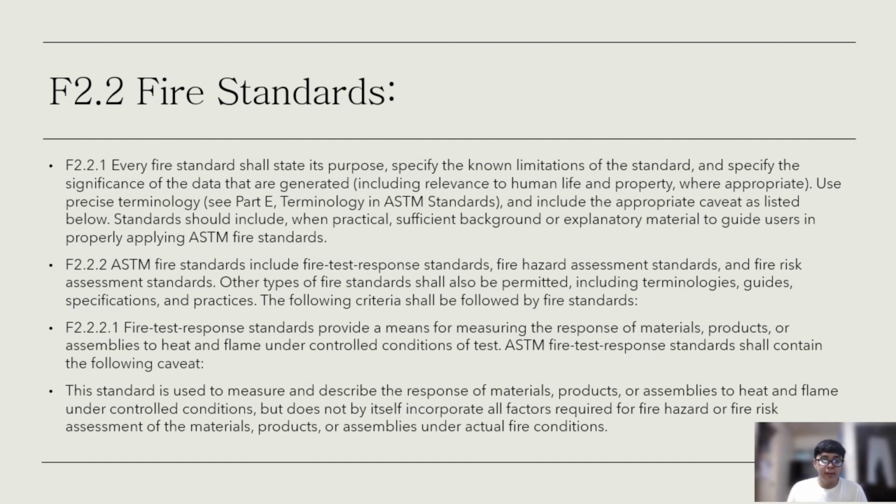ASTM fire standards include fire test response standards, fire hazard assessment standards, and fire risk assessment standards. Other types of fire standards shall also be permitted, including terminologies, guides, specifications, and practices. The following criteria shall be followed by fire standards. Fire test response standards provide a means for measuring the response of materials, products, or assemblies to heat and flame under controlled conditions of test.